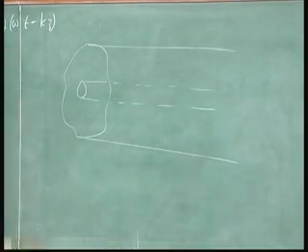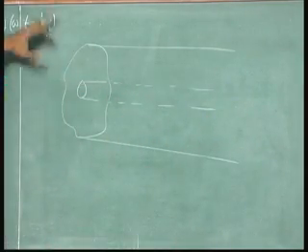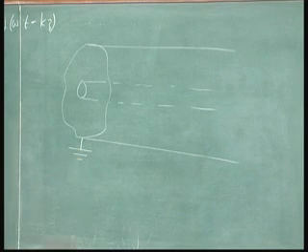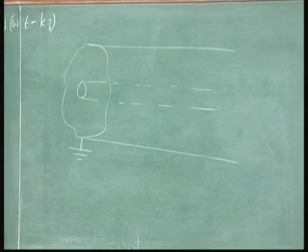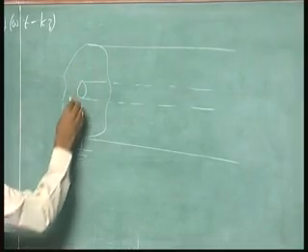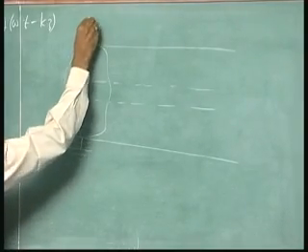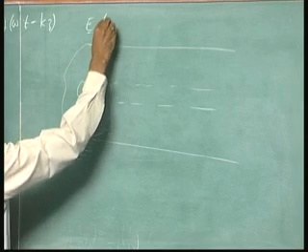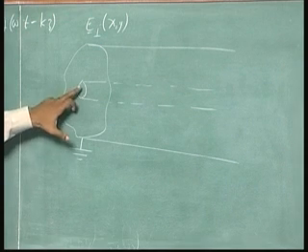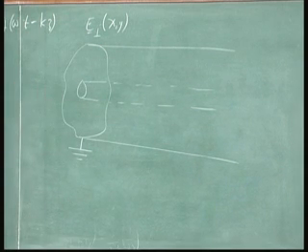So, it has an inner core and an outer shield, and let us say that the outer shield is grounded. Now, I have applied this approach to it. So, I believe that my electric field E perp is a function of x and y only. I can solve for capacitance, so this is a correct approximation.